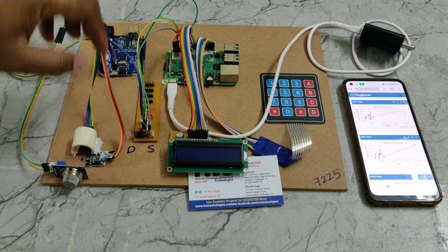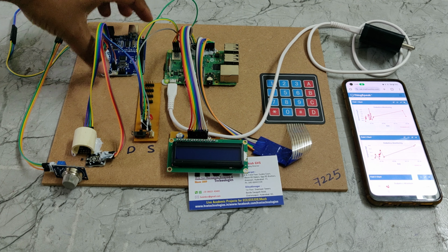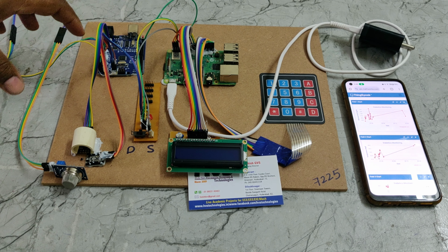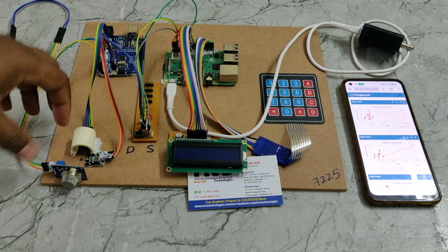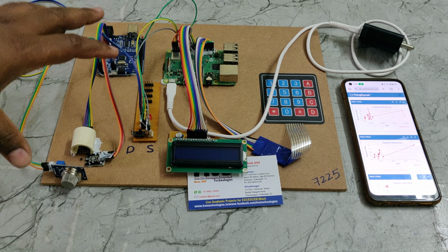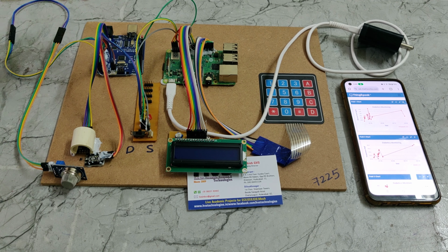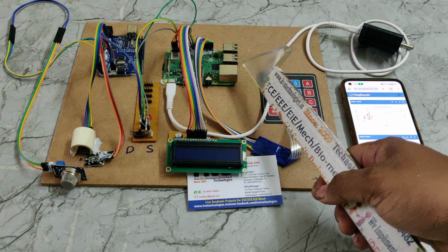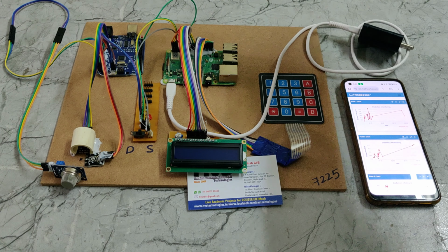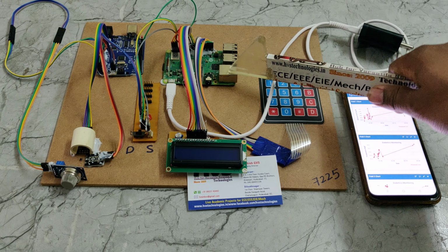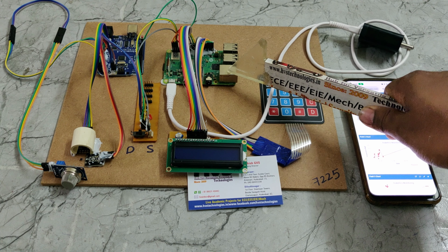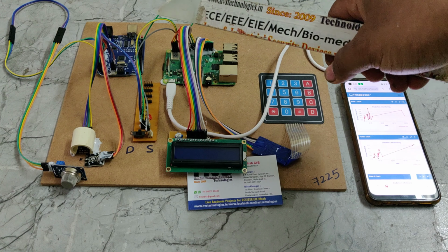So these 3 are inputs to this Arduino Uno. Here we are using the Arduino Uno just to convert the analog data to serial data. After the calculation is successfully done at this part, the system will convert this analog data to serial, as the Raspberry Pi doesn't have an analog reader. The serial data is then read by this Raspberry Pi 3B plus, and we get the string data.